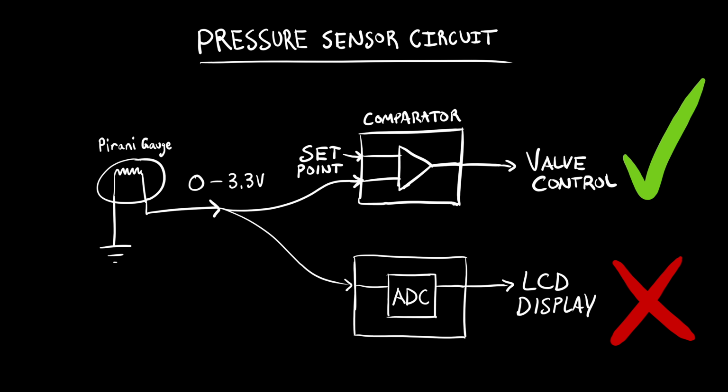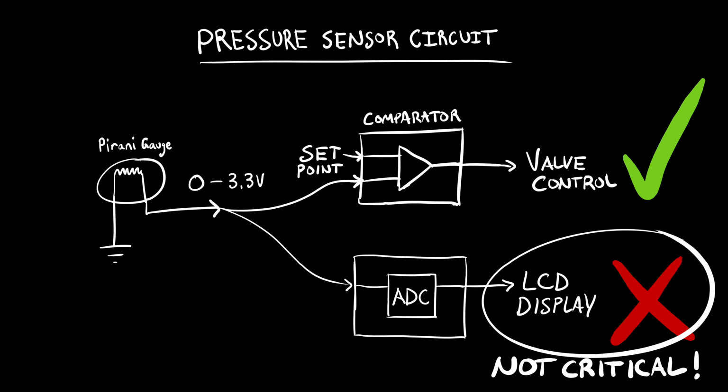Now, fortunately, this won't keep the machine from operating. However, it is pretty important that we know the pressure in the chamber at all times. Running the machine with a leak will lead to an insufficient vacuum, which at best will reduce image quality and filament life, and at worst can lead to a catastrophic failure of the diffusion pump. We really need a vacuum gauge.